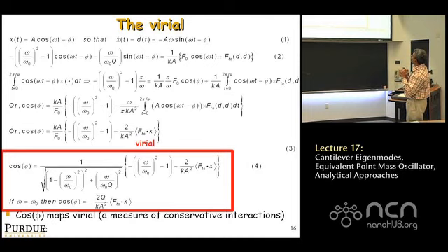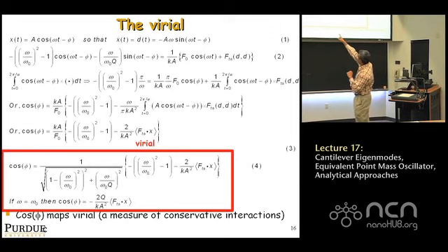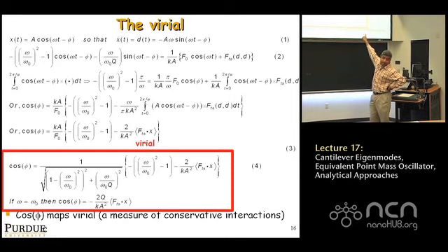If you walk through this, you actually find a really remarkable result, which is cosine of phi equals Ka over F0 times this omega 0 squared minus 1. But look at the term in the integral here. The term in the integral here is f times a cosine omega t minus phi. Now, what's a cosine omega t minus phi? Is the tip motion, x, right? The tip motion is a cosine omega t minus phi. So the term in the integral now simply becomes f times tip position integrated over the oscillation cycle.